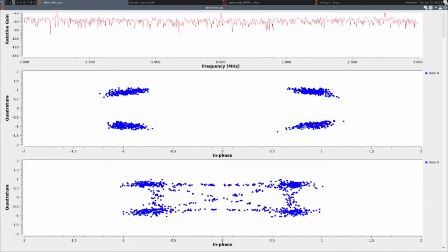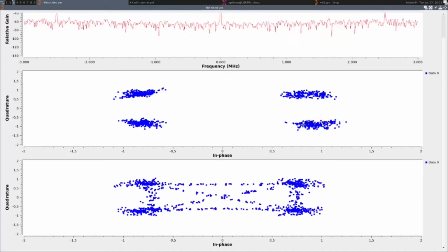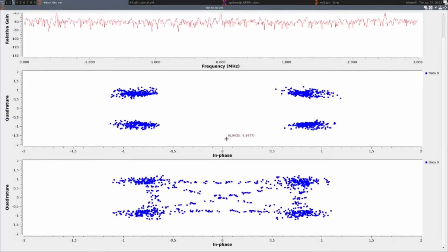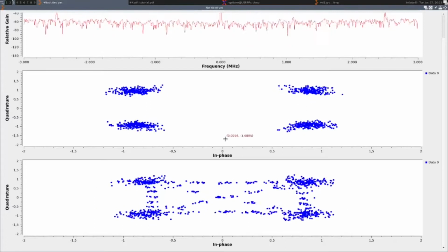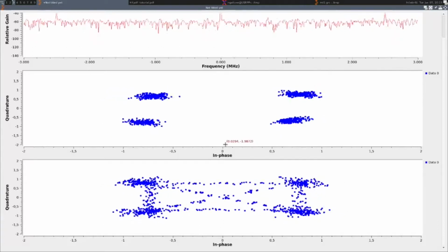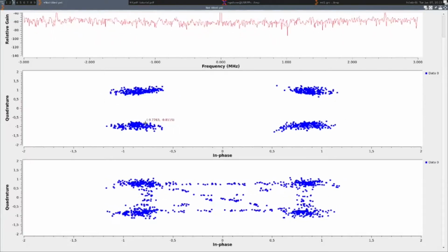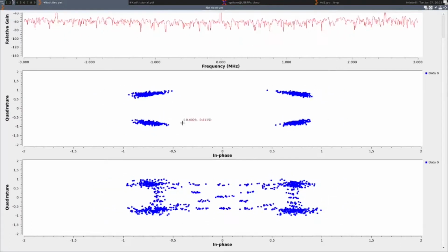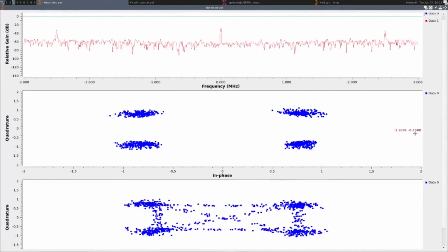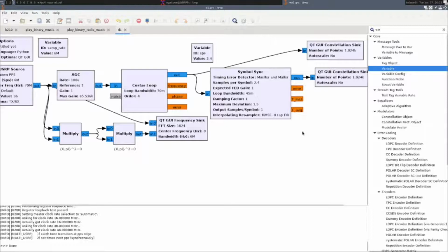Now we have the same analog bandwidth, but you see here that the challenge of demodulating is that these 4 clouds are much closer to each other than they used to be with BPSK. With BPSK, we only had +1, -1, so putting a threshold at 0 would allow you to identify which bit has been transmitted. This time we have 2 thresholds for soft bit to hard bit selection, and of course, because these clouds are closer to each other, the risk of erroneous detection is higher. So this is a demonstration of QPSK doubling the data rate at the same analog bandwidth using the FPGA.